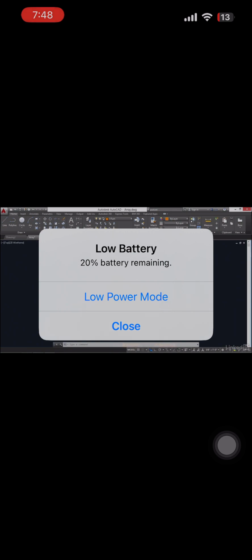So there are also 2 different kinds of arrays beyond the rectangular array that you can create. You can make a polar array that goes around a circle and an array that goes along a path. Let's try those. Go to Polar Array, select the chair, and press Enter. It asks you to specify the center point of the array. And for this, I need to use Object Snap so I can snap to the center of the circle. Hold down Shift and right-click and choose Center, and then click at the center of the circle.